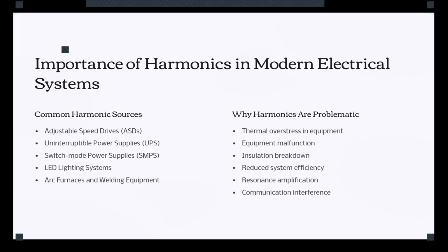You know that every physical system has a natural frequency, and if you apply an input with that frequency to that system, it would have a resonance effect and significantly boost that specific frequency input. Okay, so now imagine we have a power system that, like all other physical systems, has a natural frequency. Now, if the frequency of one of our harmonics matches that natural frequency, that means the system would significantly boost the size of that specific harmonic, which could cause extra stress for the equipment, and also could create a malfunction or misoperation in the equipment too.